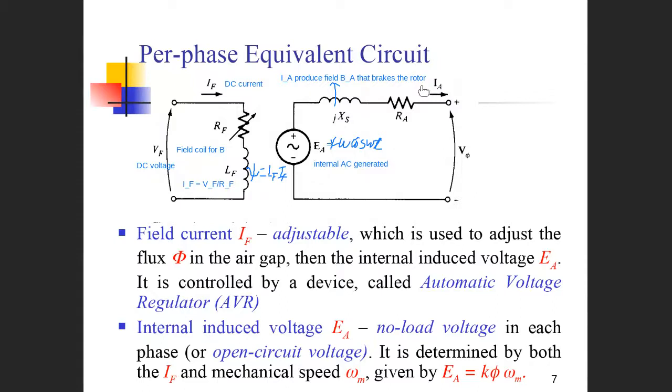The input torque is just to overcome the friction, the internal mechanical losses. Imagine that when the generator is open, although the rotor rotates, it doesn't consume much power because the input torque is smaller. That's the concept of it.